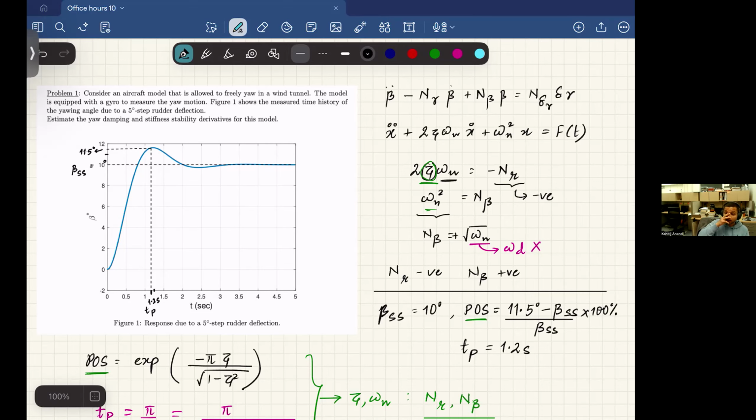We have learned to characterize the second order system using their responses to different inputs. If you give them a ramp input, or a step input, they give standard outputs, and analyzing their outputs, you need to look for the steady state value, the percentage overshoot, and the time at which the maximum overshoot happens. When you have these three data, you can go back and calculate the damping ratio and the angular frequency, and further find out the natural frequency. Okay, thank you.